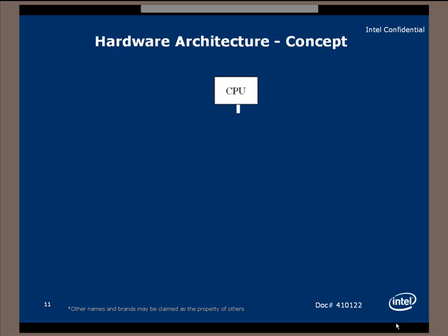So this is a block diagram of the overall Intel architecture. And again, this is a concept diagram. So these various blocks that we're going to be talking about move around inside the various chipsets. Start off with the CPU, and one of the things that's kind of important when you're reading Intel documentation is the CPU goes at the top, and that's not just a silly decision. Some of our documents are going to talk about southbound traffic, northbound traffic, and they're always kind of going back to this concept picture of the CPU on top.